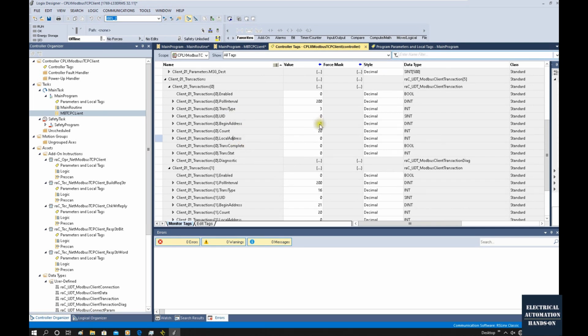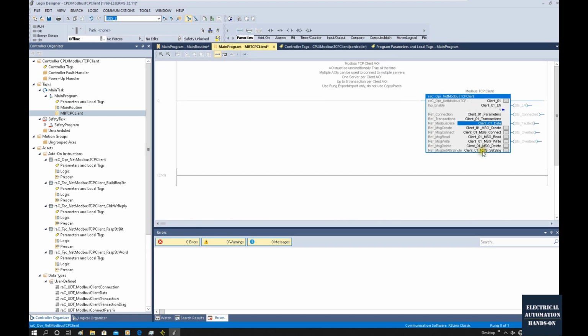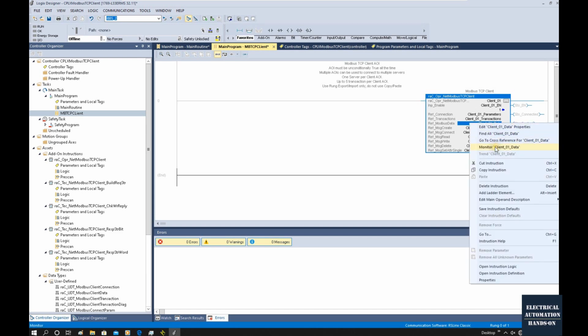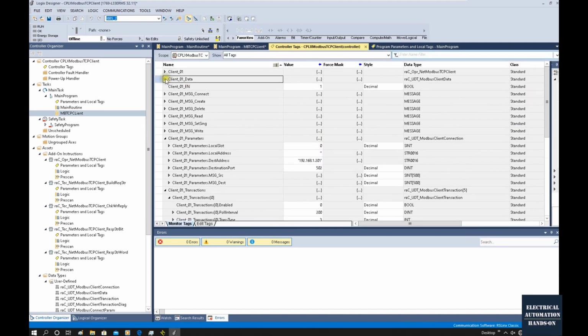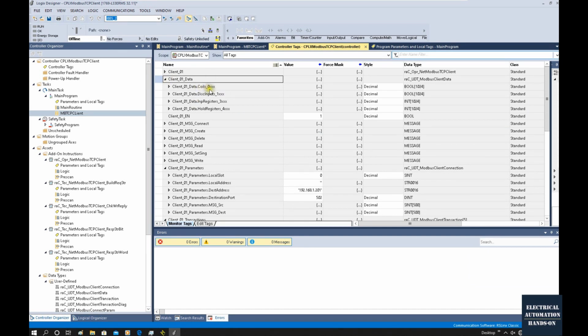As we know, this address, 400,000, is the Modbus address. But there will be an image address, a mapping address, reading from the Modbus address to our PLC local address. The local buffer address, if we go back from this function block, we will see is the PLC Modbus mapping address, this memory area. So let's right click this monitor, and we will see here. It has the coil, discrete input, input register and holding register.